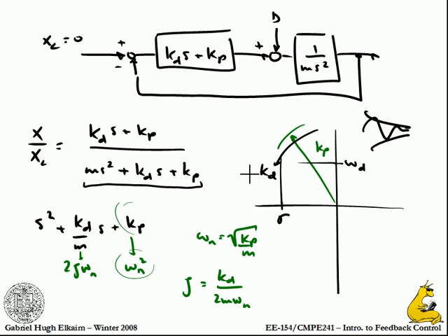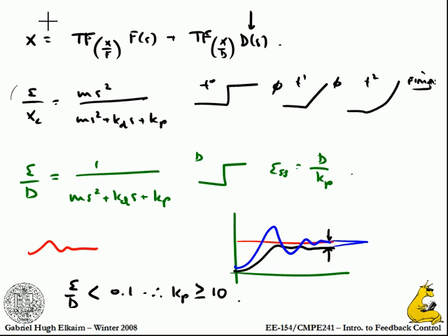One of the things I did here, which was kind of interesting, was we showed that x, in this case for the satellite, is a transfer function of x to f of s, and a transfer function x to d of s. The f is what I'm controlling with my feedback. I'm saying I'm going to make f some function of x. And so if I write the error to my command, I get this shape, which looks like a type 2 system. Then I have a finite error to a parabolic input, but 0 error to a ramp and 0 error to a step.